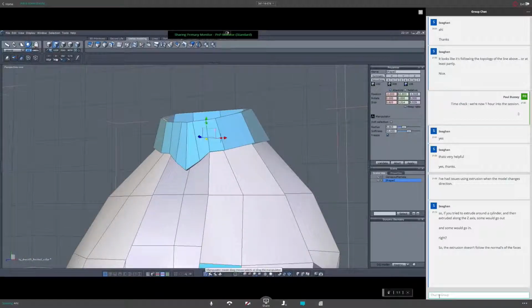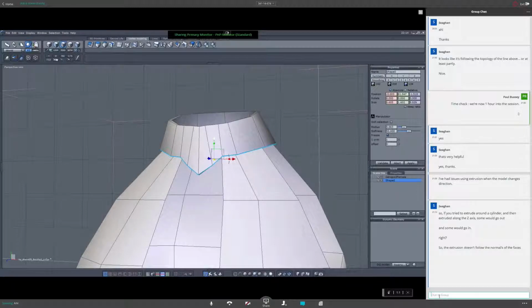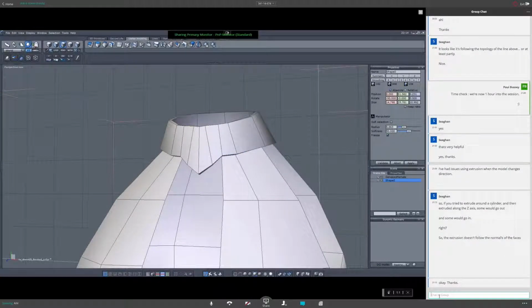And if that doesn't work to your satisfaction, you select the lower leading edge of your outer polygon row, and then you can move this, scale this. You can do the same to the top edge here. That's what I would do. There's no really automated answer for this. So you will always have to invest some, I would say, manual labor to get it looking right.